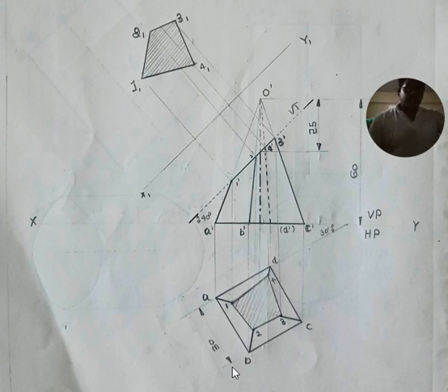And then it is a pyramid. When I see from the top, along with the base, the four slanting edges and the apex are all visible before sectioning. So you have to draw that also. To represent the slanting edges, just connect the base corners diagonally. These diagonal lines intersect, and that is our apex point. Then from the apex, lines go to the base corners, representing the slanting edges.